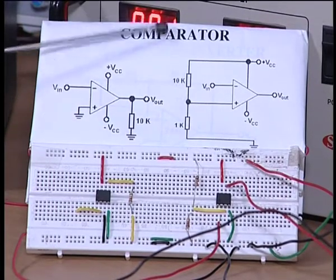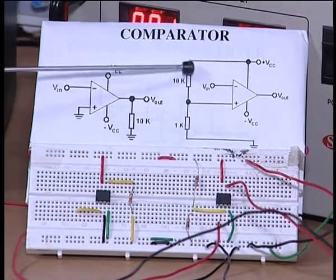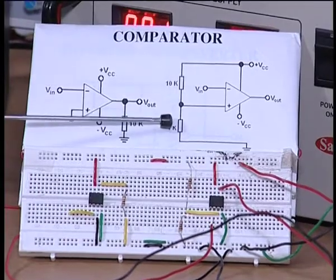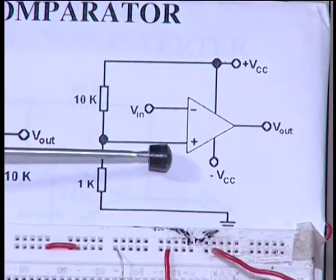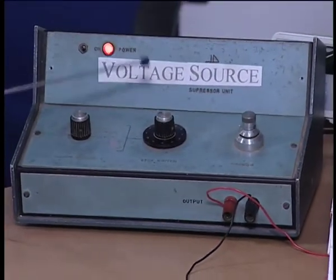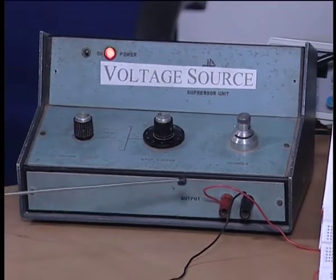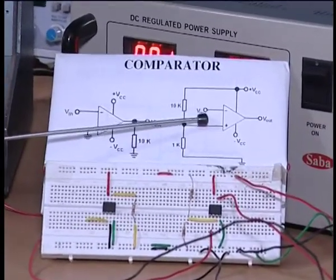Here this is the comparator. I have put two circuits here. I want you to first concentrate on the circuit to the right. You have a potential divider, a 10K and a 1K, and the midpoint of that is connected to the plus input. To the inverting input I am going to give an input from a millivolt source. This is a familiar millivolt source which we have used in a number of our experiments, and I can vary the output voltage by making use of these knobs, and that is connected to the circuit at pin number 2, which is the inverting input.